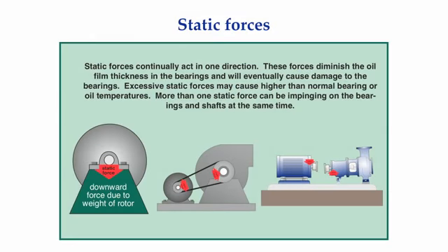By definition, static forces always act in one direction. A classic example of a static force is the downward force on a bearing due to the weight of the shaft. Another example of something that puts static forces in a bearing is belt tension.